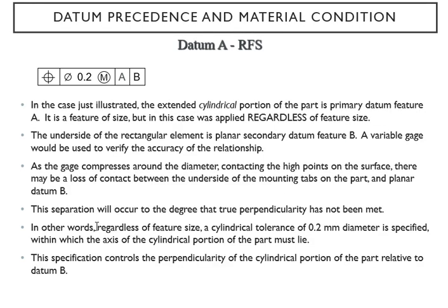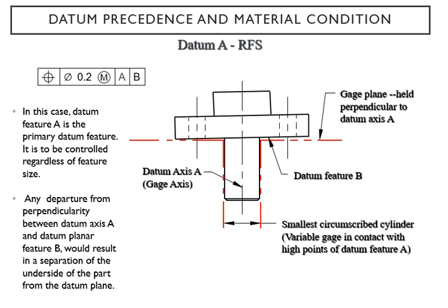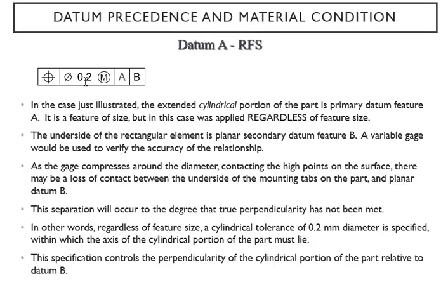Okay, and then your RFS. So in our example, your cylindrical tolerance is 0.2 because it says so right here. I also stuck it in here so you don't forget it. And of course we are in metric, that's why you have a 0 in front of the decimal. So when you look at it, don't wonder, am I in inches or am I in metric? It is in metric, you know that. If it's in inches, we won't write the zero. Americans don't write the 0 in front of the decimal. I have already told you about that several times.